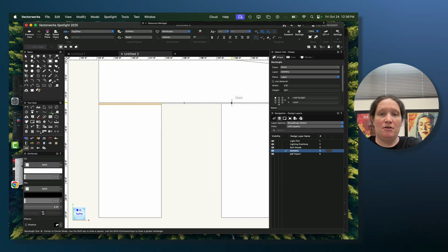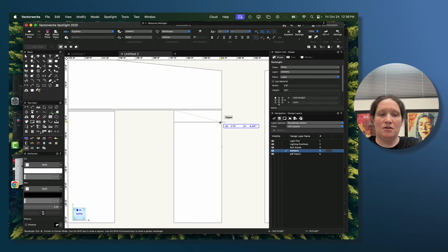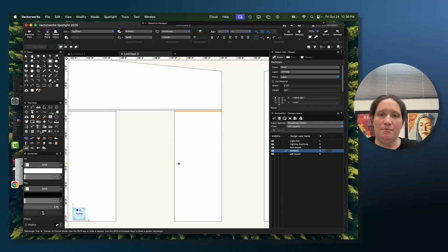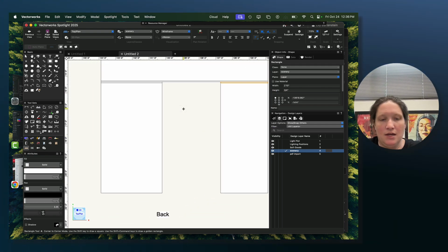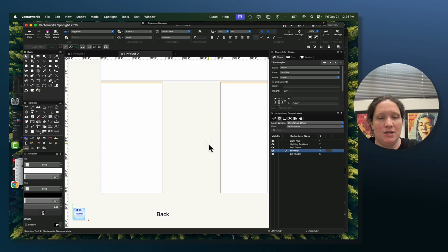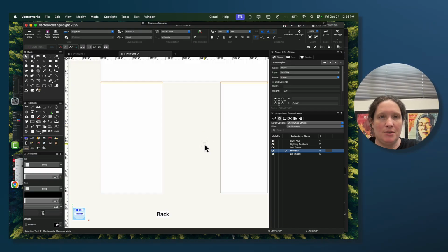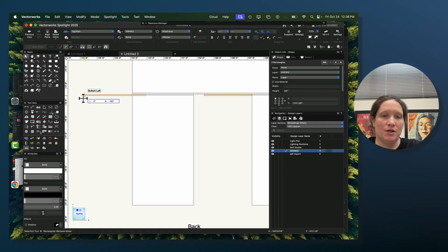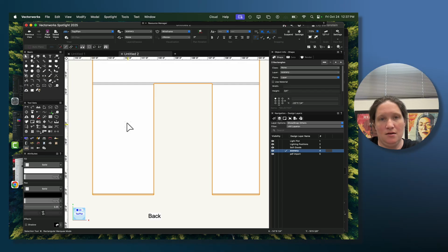Okay. I'll do the same thing over here and on all of the bottom edges, right? So this, hit tab because I want to keep that, minus 3/4, and tab again and then click. Okay. So those two are great. I can actually copy and paste. So if I hit my X key to get back to my cursor, I can select those two pieces. I can Command C, copy, Command V, paste, and then I can pick up from this bottom corner and I can snap that in, and that will also replicate that to the bottom edge.